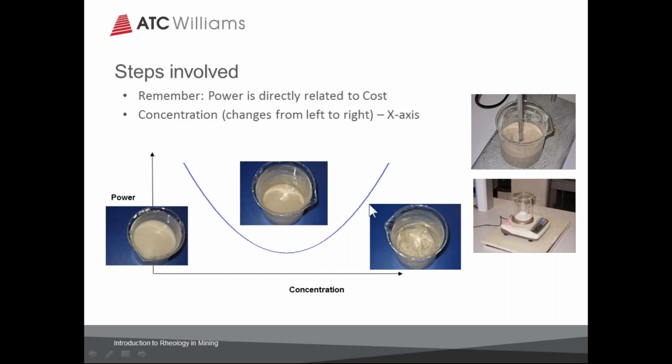If we have a very high concentration, the pumping power is also going to be quite high because we have such difficult viscous material to pump. And as engineers, we're always looking for where the optimum is and how close we can get to that operating point. And that's what we're going to look at, these three: a low concentration, a medium concentration, and then a high concentration.